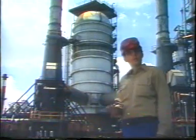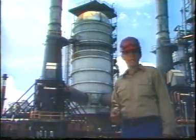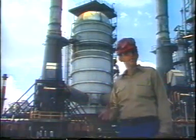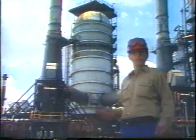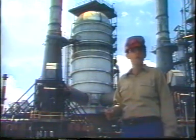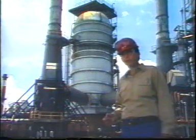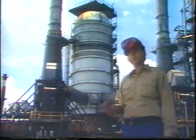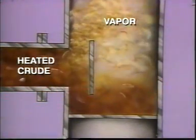Vacuum columns are generally used to distill very heavy compounds that have very high boiling point temperatures. If we distill these compounds at atmospheric pressure, we'd need to use an excessive amount of heat in order to vaporize the large molecules. These high temperatures, in turn, could change the structure of some of these molecules, thus changing their characteristics. We can obtain a better and a more economical separation if we moderately heat the liquid and then feed it into a column that is under a vacuum.